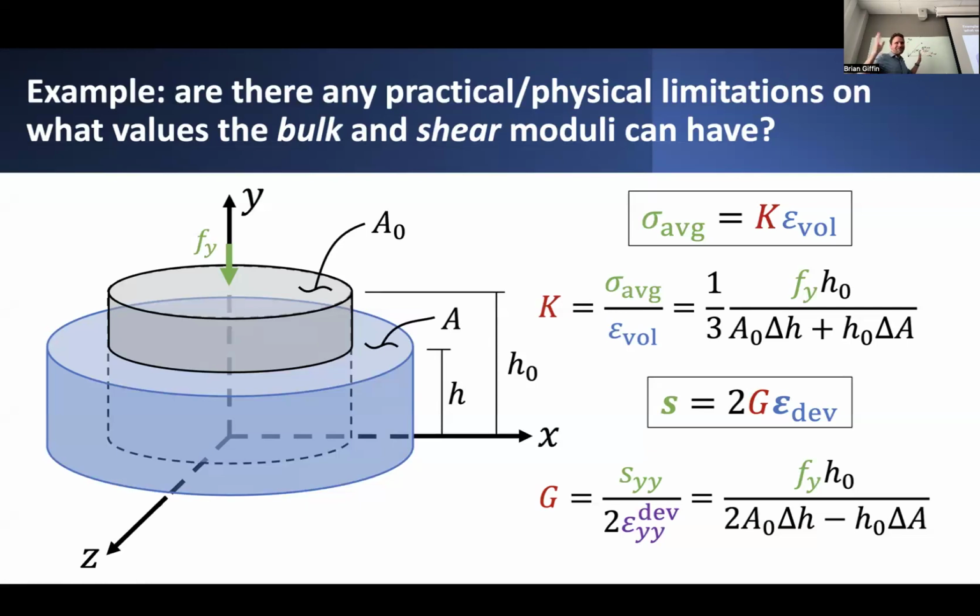I mean, there may be some mechanical engineer working on interesting metamaterials that exhibit unusual negative stiffness properties, but for almost all physical materials, these stiffness coefficients, both the shear modulus and the bulk modulus, and Young's modulus, Lamé's constant, and all those things, should really be positive values. And again, it boils down to this. If you pull on something in one direction, you expect a corresponding stress to develop in that same direction. That's a fairly intuitive result.